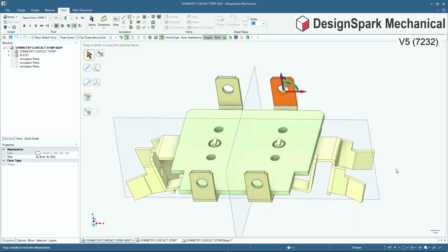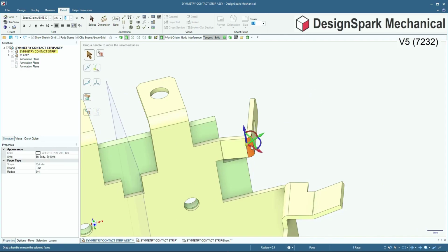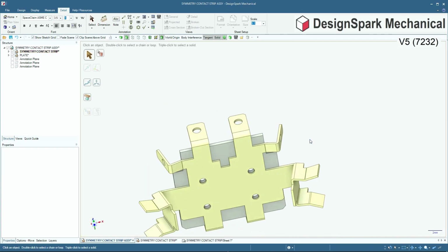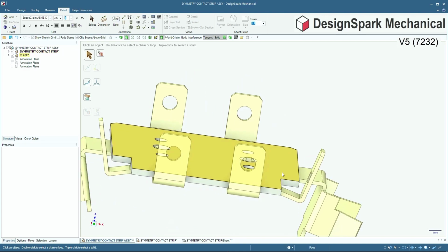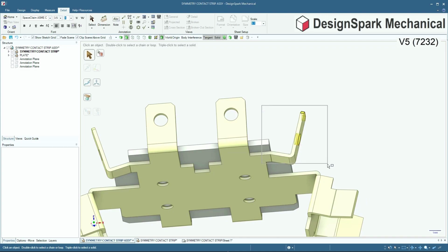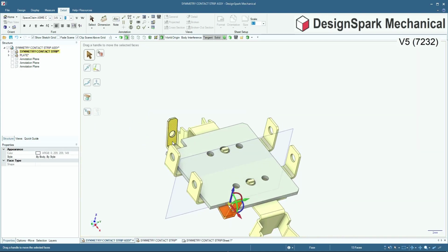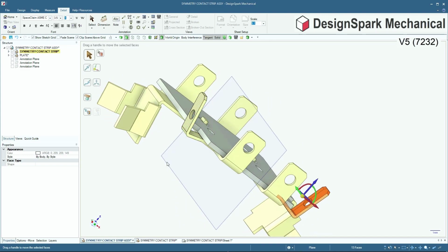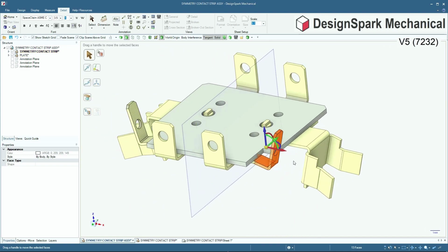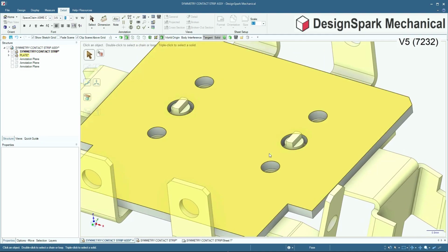Same over here really. Let's just make this the active part. Now it's active, which means effectively that I can't pull on other faces that are grayed out, which is fine. So let's just do a box selection. And here you see a box selection of that tang. That's good. And again, the mirror plane and also the graying or the texturing of the related linked faces shows up. So I can pull this and I get a duplicate change, which is nice.